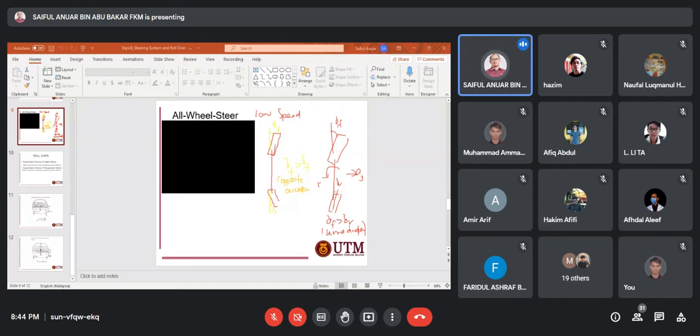But basically, this advanced or active steering system is actually based on power steering, and nowadays the power steering is based on an electric motor. A long time ago, during the early introduction of power steering, manufacturers tended to use hydraulic power steering because at that time the control algorithm technology for the electric motor was not as advanced as today.